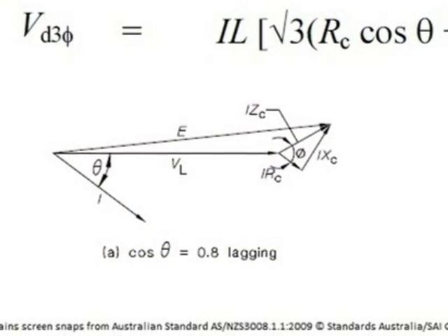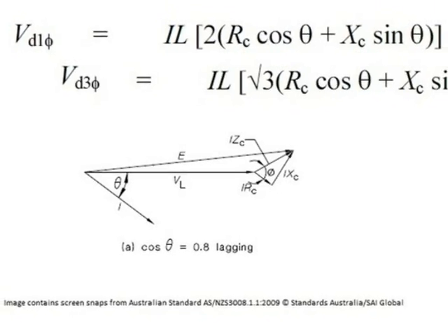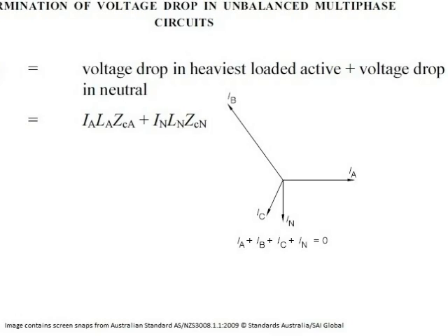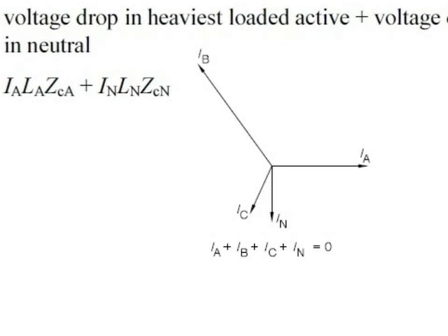Again, just another example of another application for volt drop, which is using the load power factor. Then we have this formula here, which we can apply to multi-phase loads which aren't balanced.